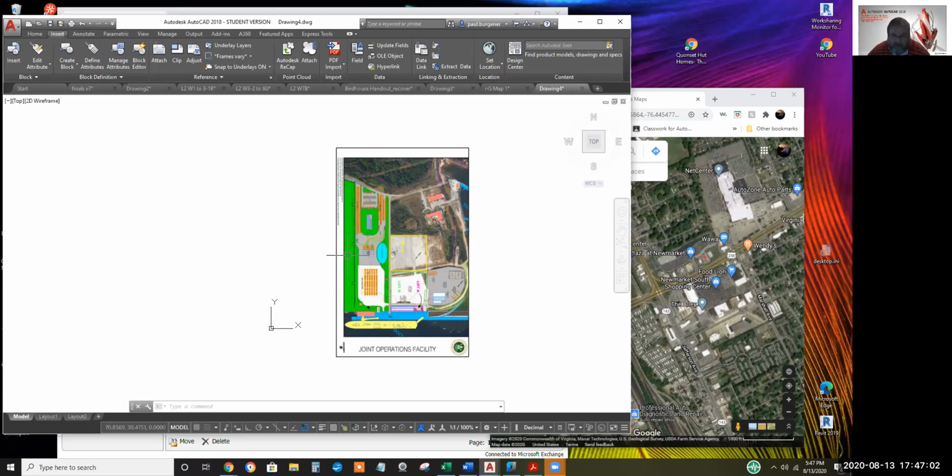And if you have a broken part in the field and nobody can find the drawings, you can scan it, scale it, and trace it in AutoCAD and develop the manufacturing drawings just out of the scan, scaled to full size.